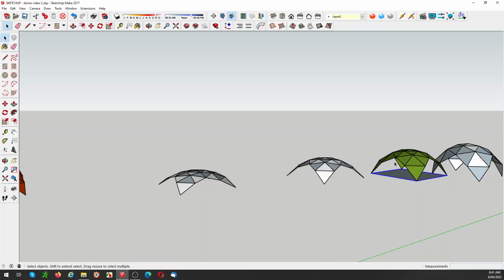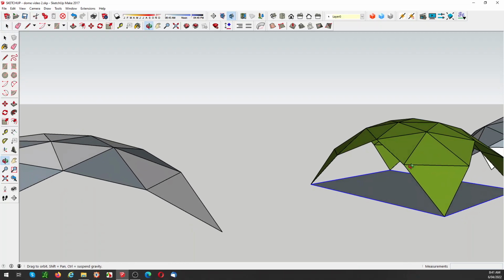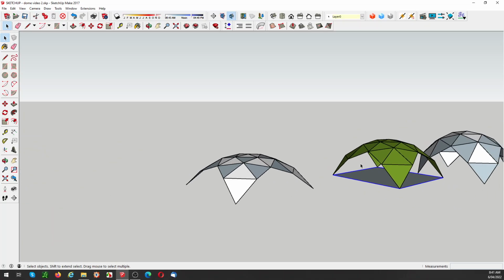You want around about the height of the first leg, the line of the first leg, you want that around 2 meters. 1.6 meters to 2 meters, ideally, to give you headroom. And for the area to be practical, I suggest that this point here, targeted at 2 meters, gives you sufficient room headwise and area wise to make it practical.